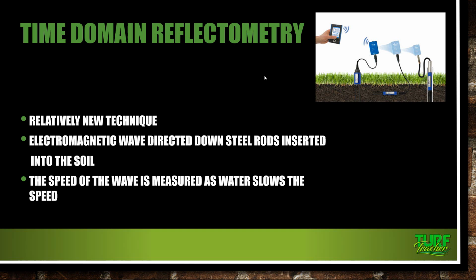This technique is based on the dielectric constant of water, which is higher than the value of the mineral soils, and so the presence of the water slows the speed of the electromagnetic wave slightly. Even the salinity can influence the readings.